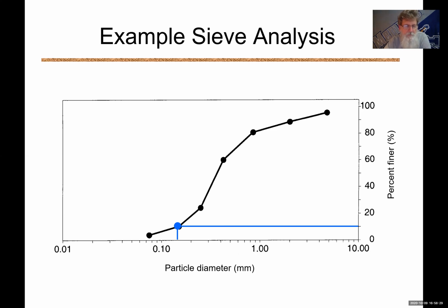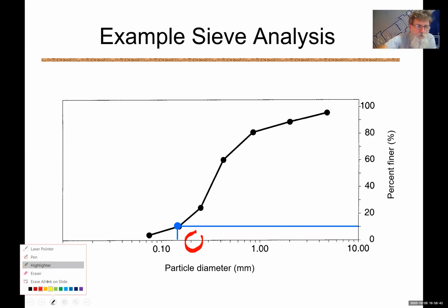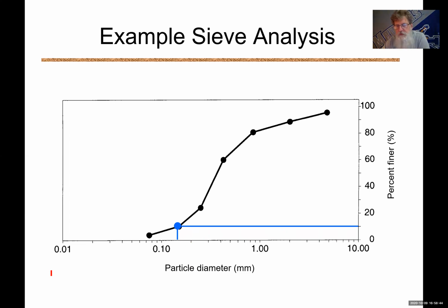So now you can see that I'm looking at something between 0.1 and 0.2. I just want to emphasize that first tick would be 0.2. So it's between 0.1 and 0.2. So we know it's going to be 0.1 something, and you just have to guess. It's kind of in the middle, so I guessed 0.14. Remember, the numbers are shifted to the right, just like the scale is here.